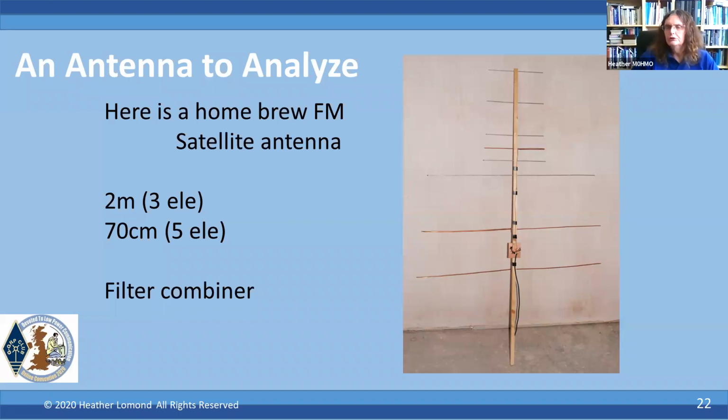Yes, you're inherently limited by the design of these things. Obviously, the more elements you add, you change it. If you go for a folded dipole, this antenna, you can't quite see it, but this is actually a half folded dipole. And again, that changes the feed impedance.